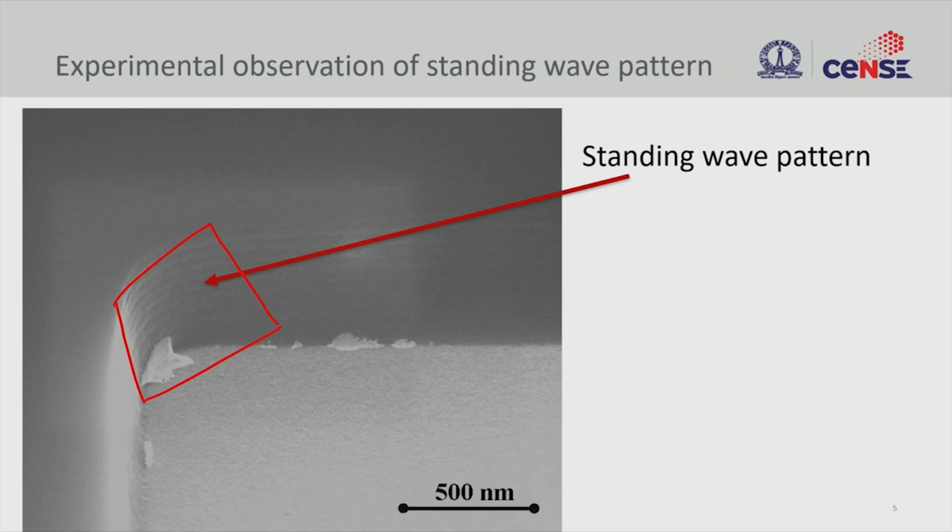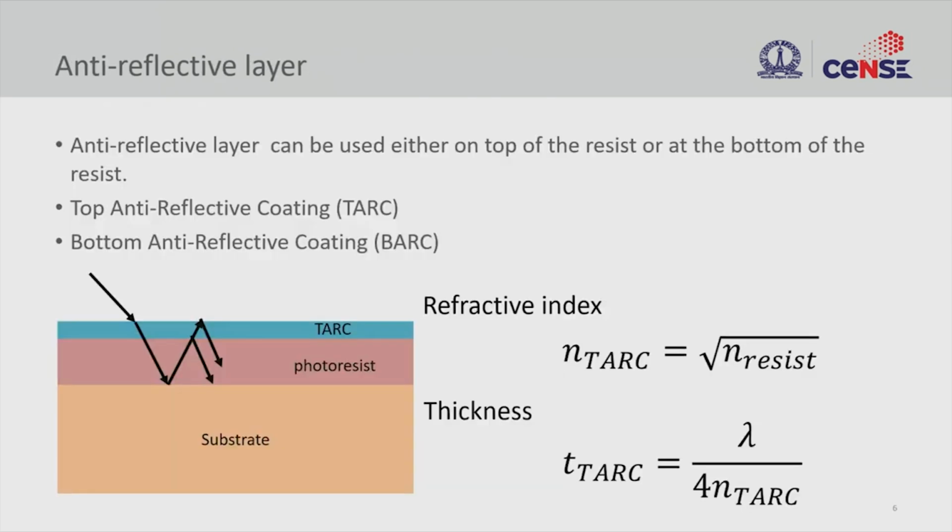Okay. And if you are going to use this for dry etching, you are going to transfer the non-uniformity that you have on this photoresist onto your silicon or underlying pattern. Okay. So, you have to be really careful about this reflection, right, that you get from the substrate to avoid this.